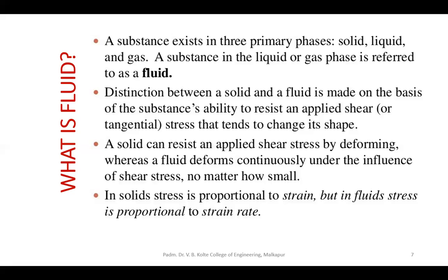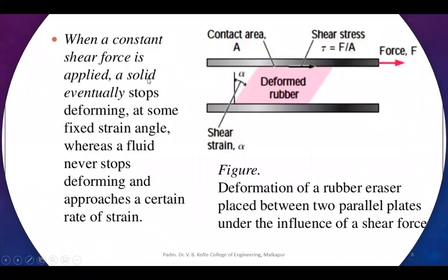Okay? In solid, stress is proportional to strain. This point is important, remember it. In solid, stress is directly proportional to strain, but in case of fluid, stress is directly proportional to shear strain, or it may be called the strain rate. Okay? So when a constant shear force is applied, a solid eventually stops deforming at some fixed strain angle, whereas fluid never stops deforming and approaches a certain rate of strain.